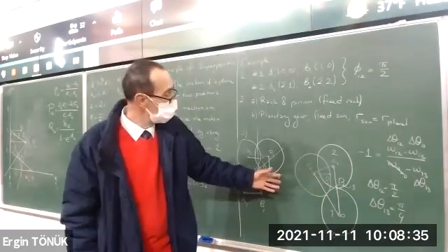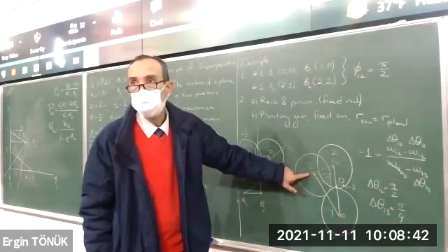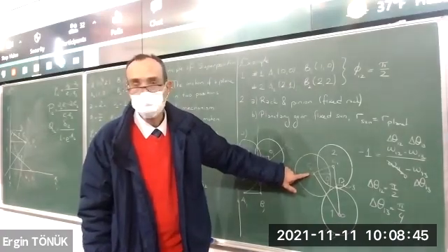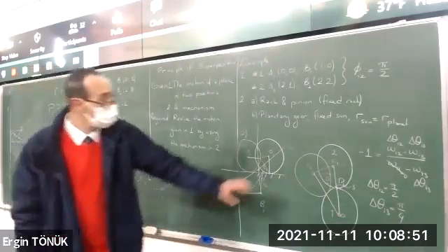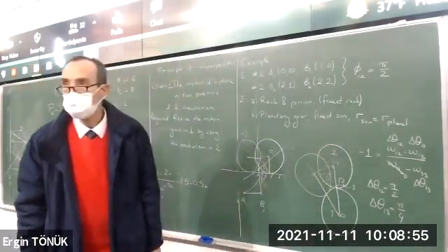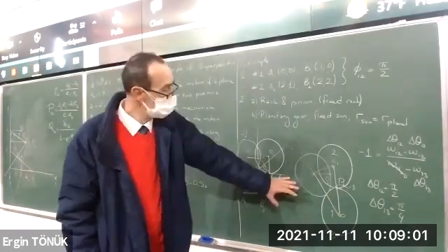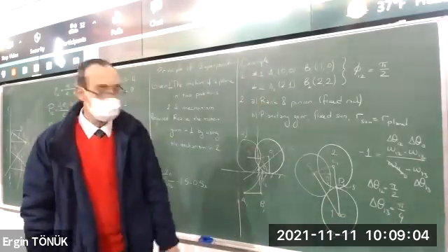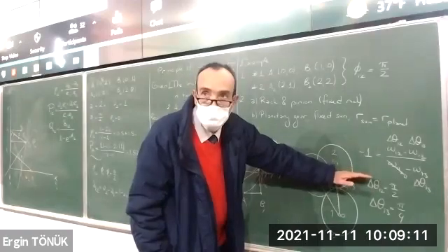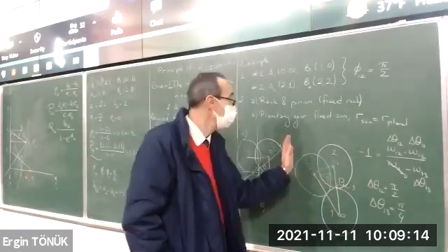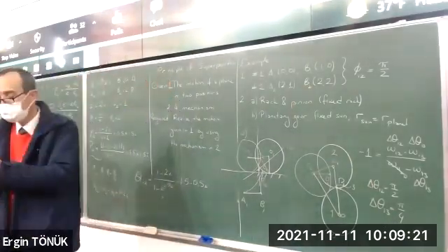But it's rotating about C, and C is moving as well, so it's not a simple fixed axis rotation, it's a general plane motion. So you have to find, by using any 2 points which are suitable for you, the pole of this planet. Then when you find it, you have the pole of this as well, coincide the 2 poles, see where A1 and B1 are going to come in this position. I don't know, maybe it's here or maybe there. Just weld it. When you rotate it, it's going to come to this position. Okay. Any other questions?